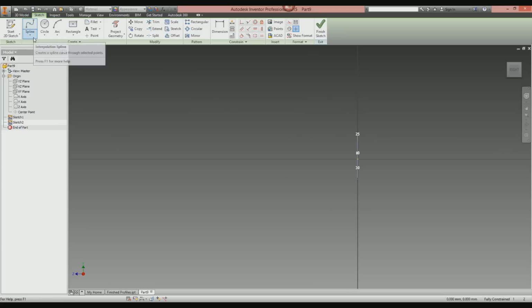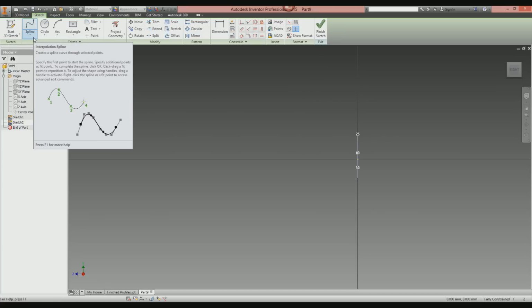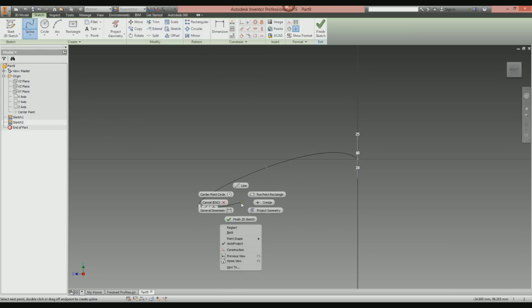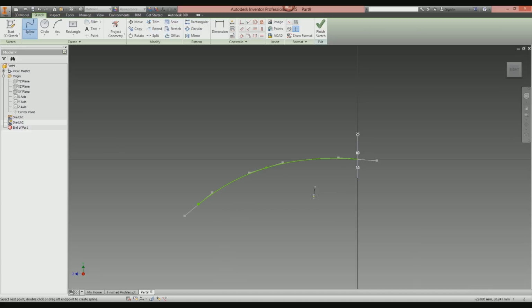It totally depends on what you're doing. Obviously I can't explain every eventuality of sketch line that you can create. So what I'm going to do is create another spline. I'm going to start at this point here, and I'm going to come maybe here and then down to, let's say, there. That'll do. That's going to be the center line for my loft profile.